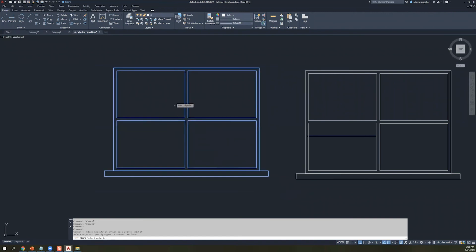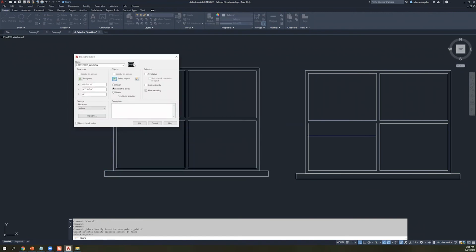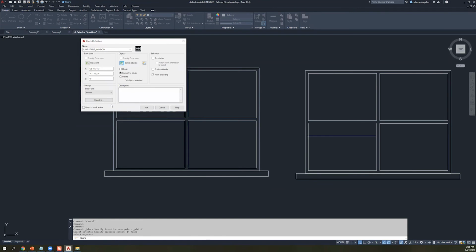And if I'm done, I just right click to get back to my option over there, and it's already pulling in a thumbnail, which is awesome, right? And then behavior over here, I'm not going to really talk about annotative scaling here today, but you do probably want to keep allow exploding on. That's usually helpful. And that's pretty much all we need over here, right?